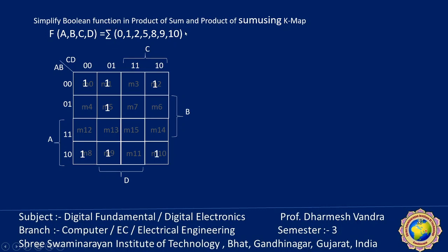Sigma is the sum of product, SOP. Min terms are there, not max terms. If max terms are given, we have to put 0. So first we will find the sum of product. Consider these min terms, the outer all 4. So it will become B dash D dash. Now these two match with the lower two. It gives B dash C dash.